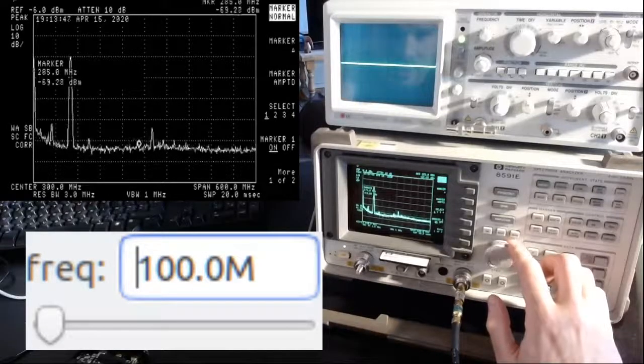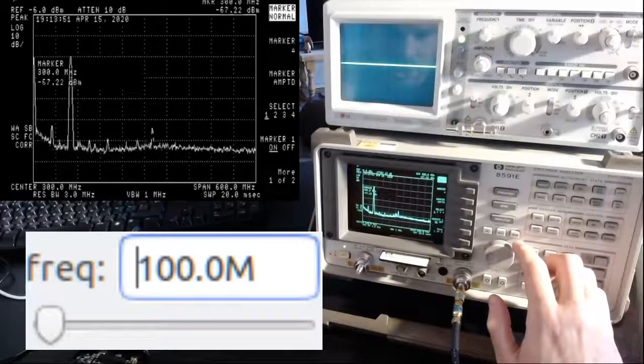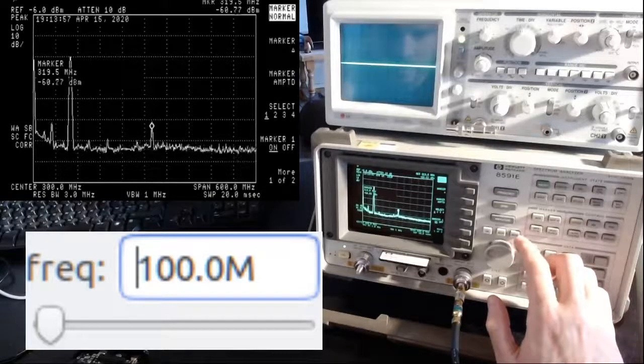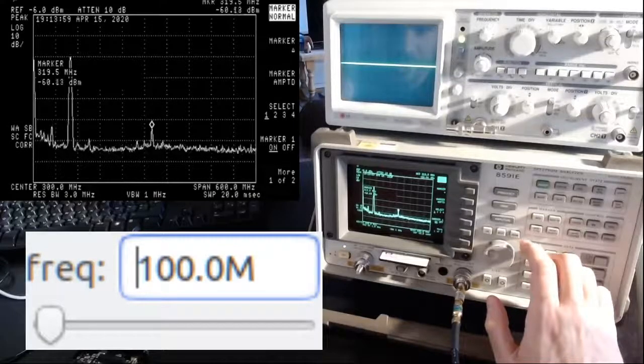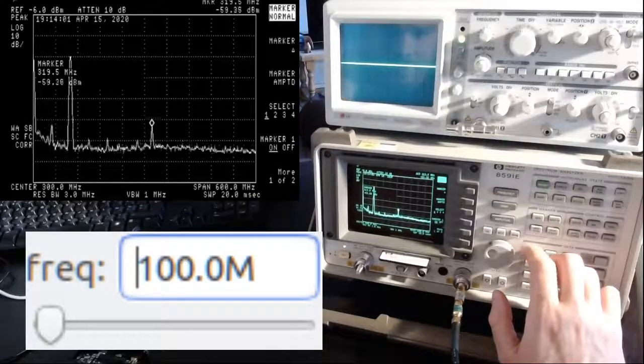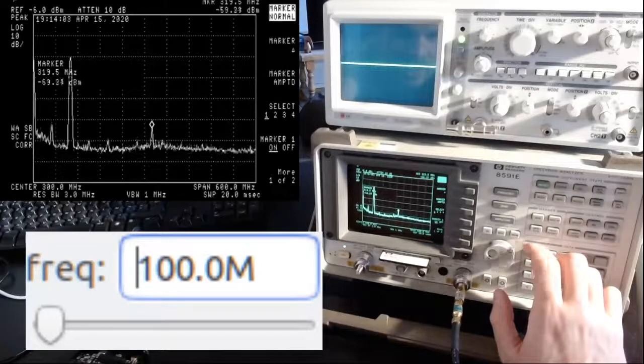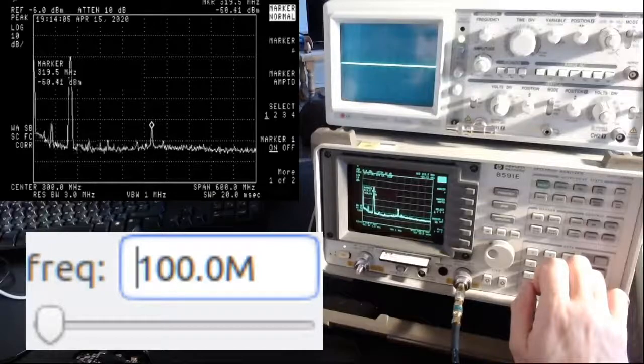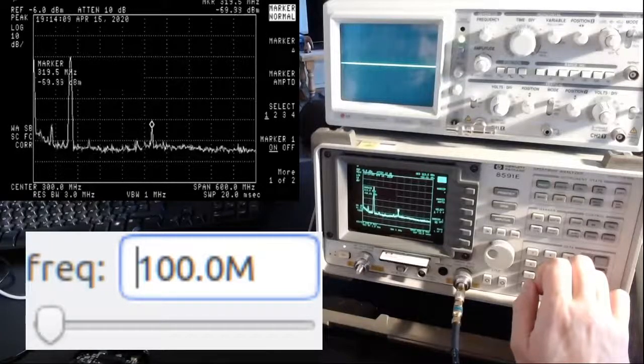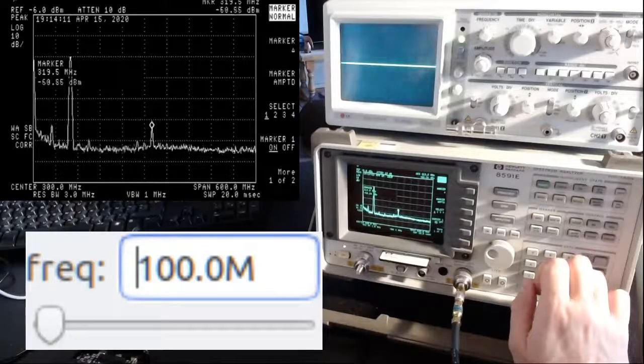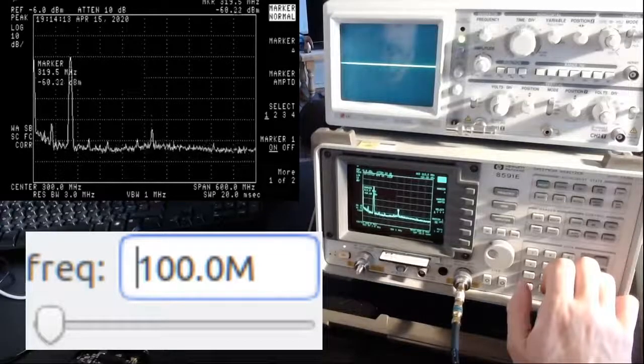Here is the position of the third harmonic, but this is also 40 dB down. Instead we have this 320 megahertz that must be associated just with internal noise of the HackRF. So in this case the unwanted harmonics are again 30-35 dB down compared to the main signal, so minus 30 dBc.